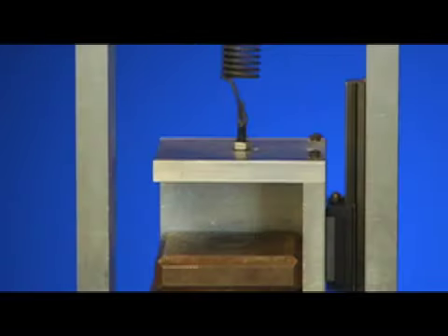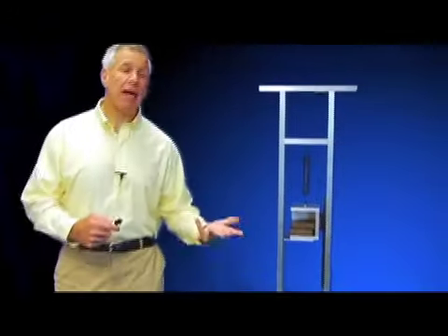How do I capture this physical effect? Well, again, how much detail do I need to understand the behavior of this system? At this point, I'm looking for insight into the behavior of the system. So typically, engineers will use a very simple approximation to friction that lends itself to easier analysis. And that approximation is what we call a viscous damper. We all have experience with a piston moving in a cylinder with perhaps holes or a small space through which fluid can travel.